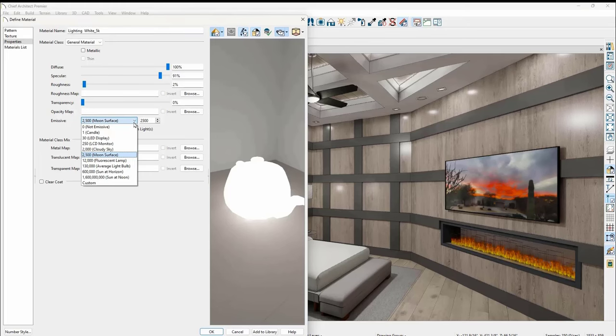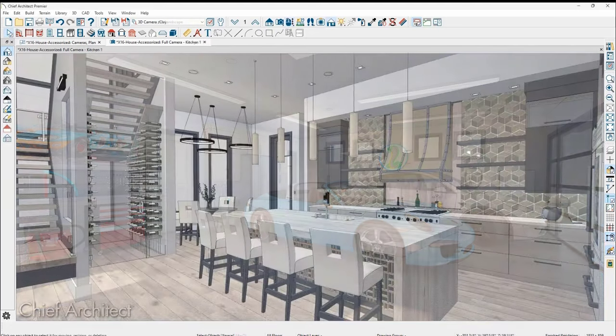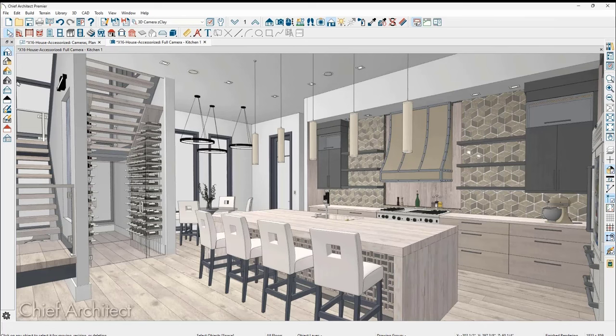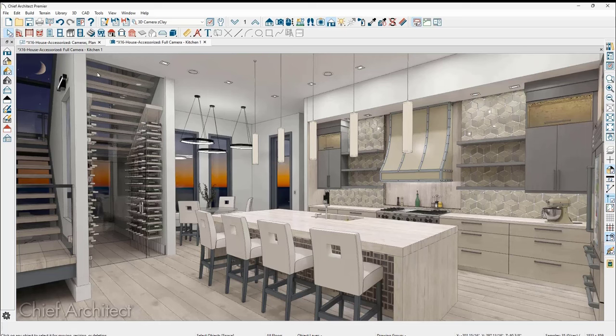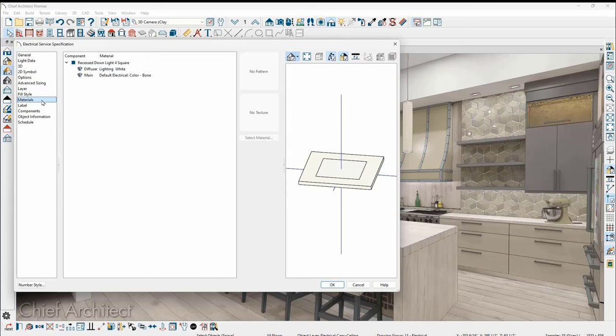The quality of physically based ray trace views can be significantly improved with area lights. In addition, a single lighting model can be used for both a standard render and a PBR render. Why? These standard renders use punctual lighting sources, which can be tuned for these views and not set overly bright. The PBR model uses the emissive area lights for its lighting model.